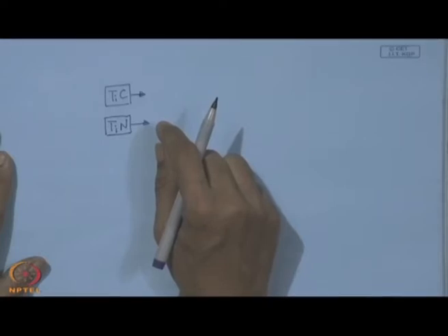So, when titanium carbide is used, the domain of application is well defined. That means, where the functional surface is subjected to abrasive wear, then we put TiC coating.